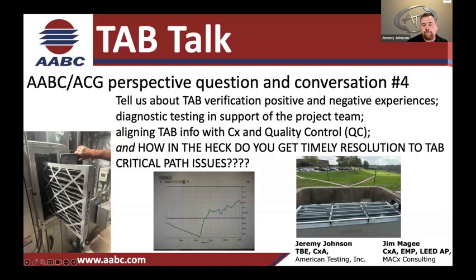Sometimes taking an extra step to say, hey, that first damper is 50% open, goes a long way in TAB verification. Because if you're a commissioning guy and you come up to this and you're like, what's going on here? The damper's wide open. What's going on here, right?